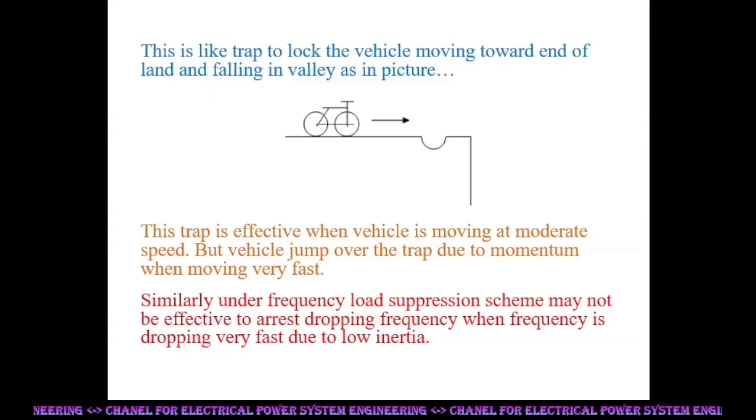Agriculture pump sets are motor load. These are not in use during the monsoon. Industrial load is predominantly motor load. This is also not working on holidays. Therefore, system inertia may be low and frequency drop due to loss of generation may be faster than normal during industrial holidays in the monsoon.